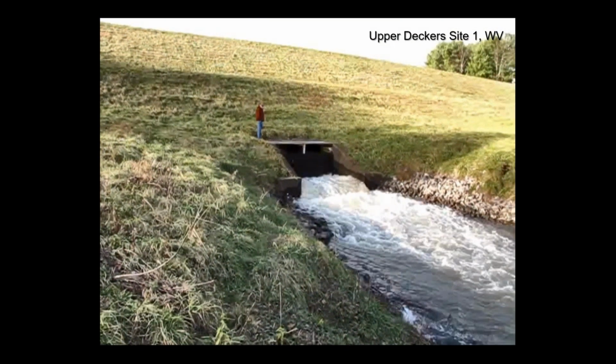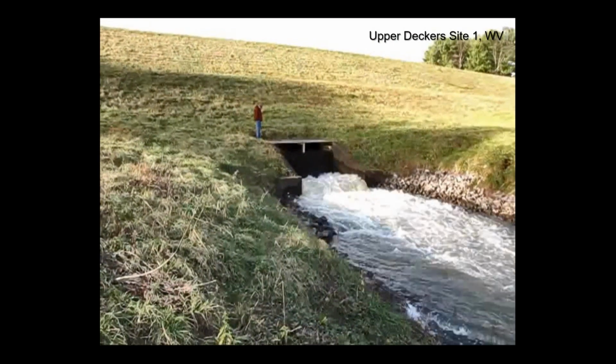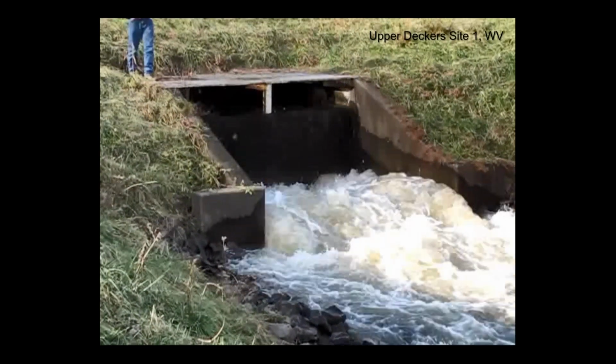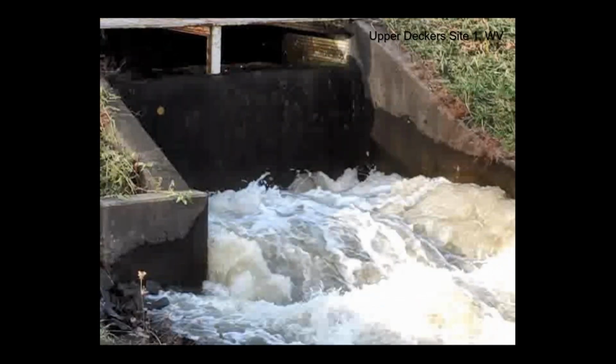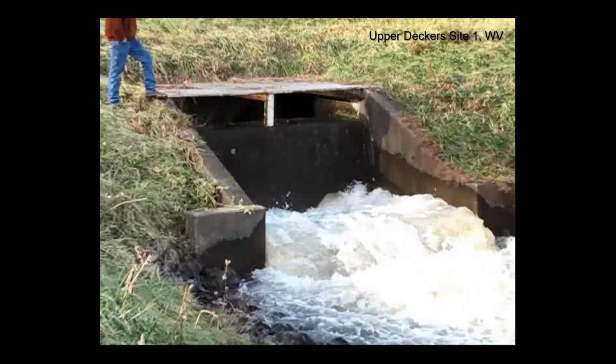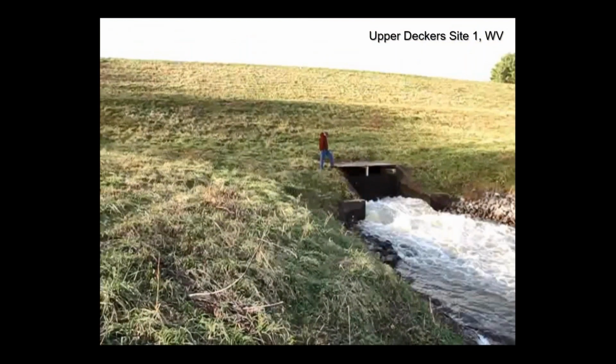This video is taken during a flood event. So if you were to go to the top of the dam and look at the reservoir, in this particular case, you wouldn't even see the riser structure because it's under several feet of water. And that's an indication that the conduit is flowing at its maximum capacity. So it's flowing full, and you can see the good job that the impact basin is doing.